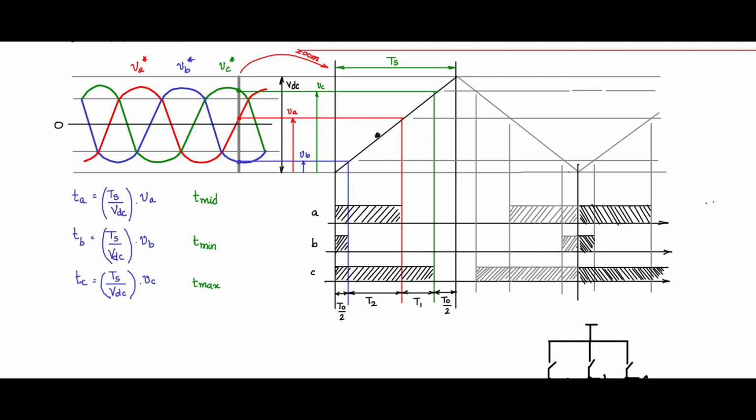What we do is we shift the 0 to this axis. So basically we are giving an offset. We make an offset down using the minimum value. I know this is the minimum value, and this region out of the envelope, both these regions out of the envelope, is the time corresponding to T0, the 0 space vector time. We saw here this is T0 and this is T0. This is the time corresponding to T0. This is the time also corresponding to T0. Both together add up as 0 space vector time outside the envelope.